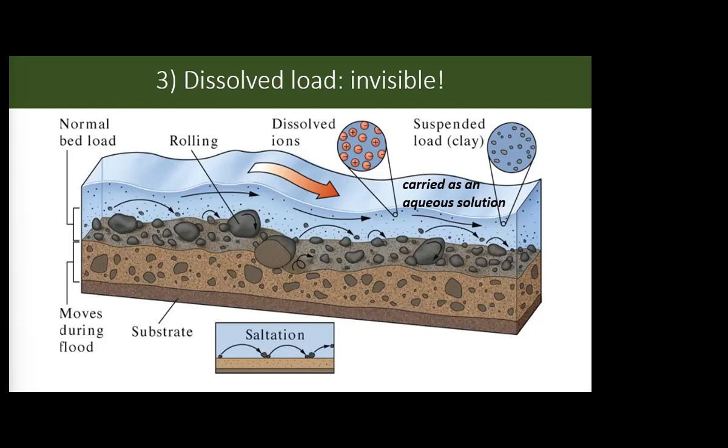We have what's known as saltation. Saltation is a confusing word. It has nothing to do with salt, nothing to do with it at all. I cannot stress that enough. That is one of the questions that I always got wrong in Intro to Geology when I was just starting out as a geologist. Always got it wrong. Saltation is where instead of just rolling, we're going to start bouncing. So it has so much momentum that it's just going to bounce on the floor of the channel. It's going to help break apart some of those rocks through abrasion, through attrition. They're going to smash into each other. This is where we have saltation, where we have a jump rather than a roll.